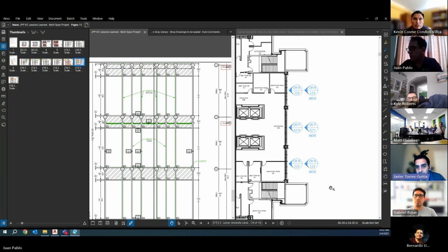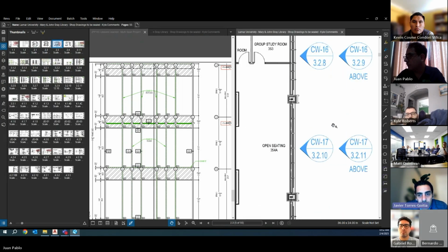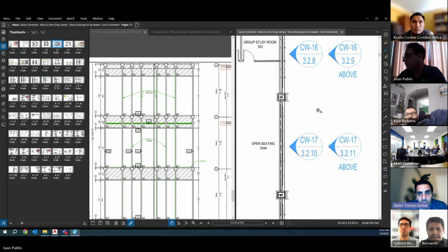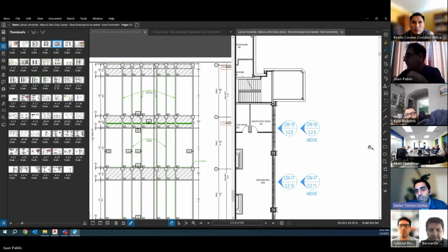I believe CW17 on the screen on the right, if you zoom in a little bit on that one, you can see the fins there on CW16. Yeah. So that pretty large box on the corner of the building goes the full height of the building. Stuart agreed that there was going to be some sort of wind shielding effect because of the building geometry there. After this discussion with Stuart, we applied only 50% of the zone 4 pressure on those, we got that to work, and that seems to be a pretty reasonable assumption to make.